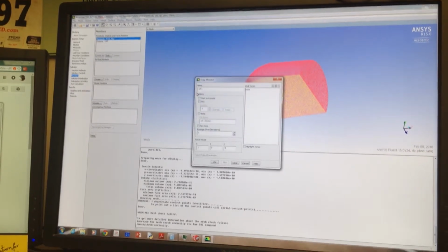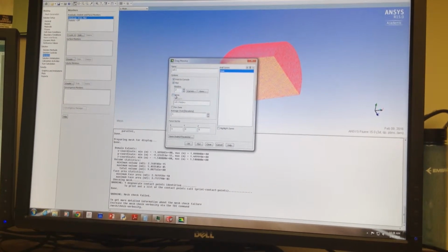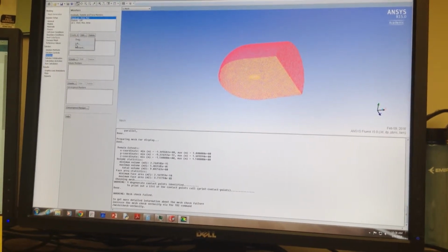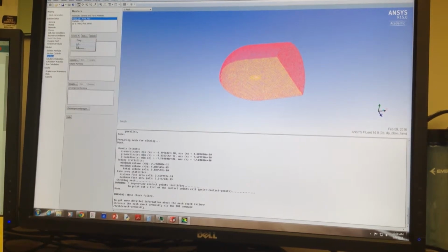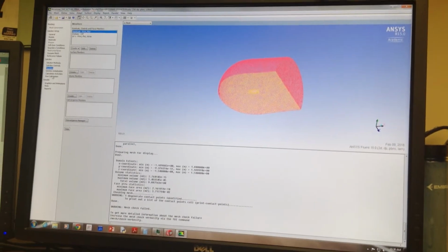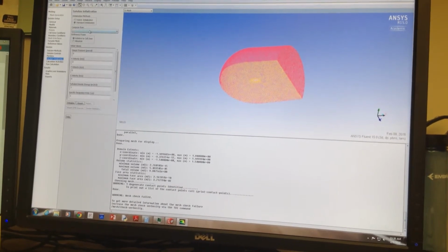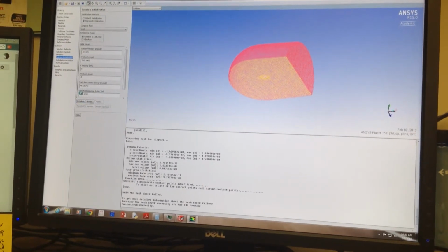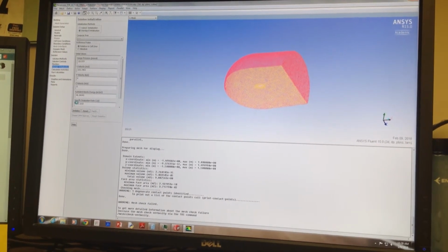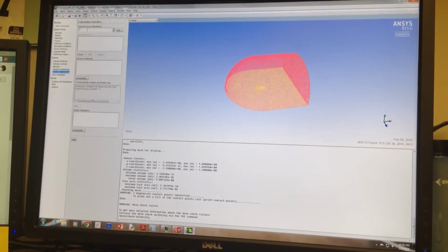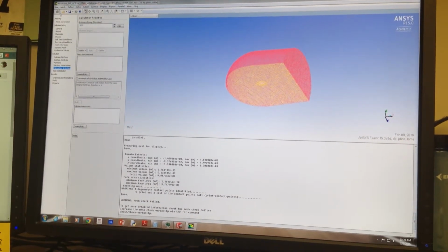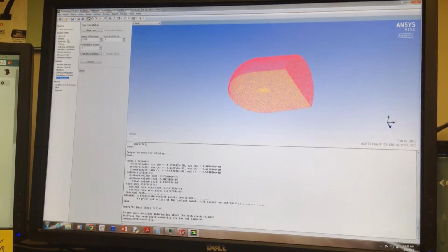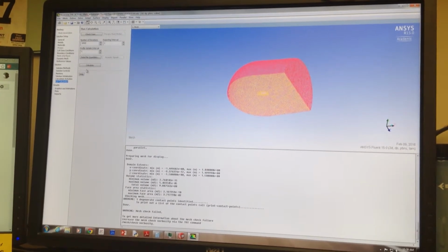You're looking for drag, right? Yes. Drag, not necessarily lift. And then just the shock. Okay, so that's alpha 0, that's what I've given. Just click on standard initialization, get back to initial inlet, just put initialize. Okay, and then save every 500 iterations. Just save. Go to run calculations, for 1000 or something, until your solution is converged. Just click calculate.